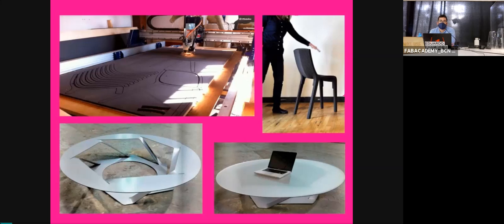Remember that in the laser cut, you have a limit on the thickness of material you can use. That basically depends on the power and the focus of the beam of your laser. Usually that maximum is not specific, it's based on the edge quality that you want to have. But let's state that for a more or less good and accurate laser cut, you never go higher than 8 or 10 millimeters of material thickness.